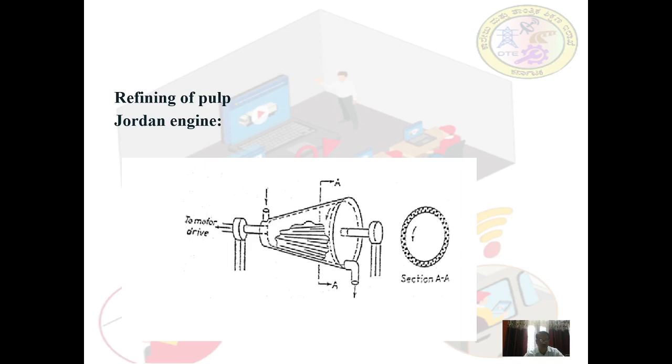After beating, some additives are added to get the desired properties to the finished paper. Additives like fillers, sizing materials, and dyes are usually added. Alum is added to coat the fibers and coagulate the material present.